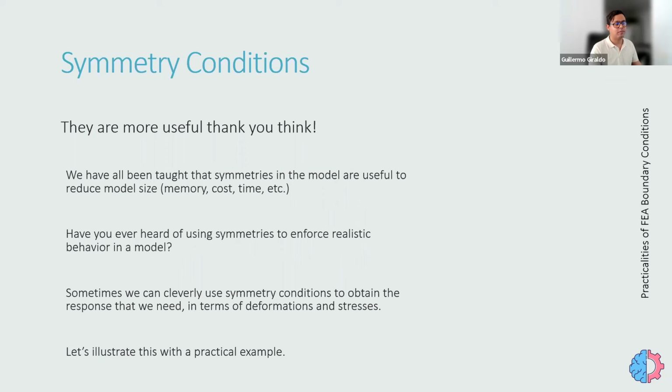But there is also a problem of over-constraining the model: constraining it in directions or deformations that do not happen in real life, and inducing a response, stress distribution, or deformation modes that are not realistic, just because our boundary conditions, or these interactions with the surroundings, are not just fixed, infinitely rigid supports.